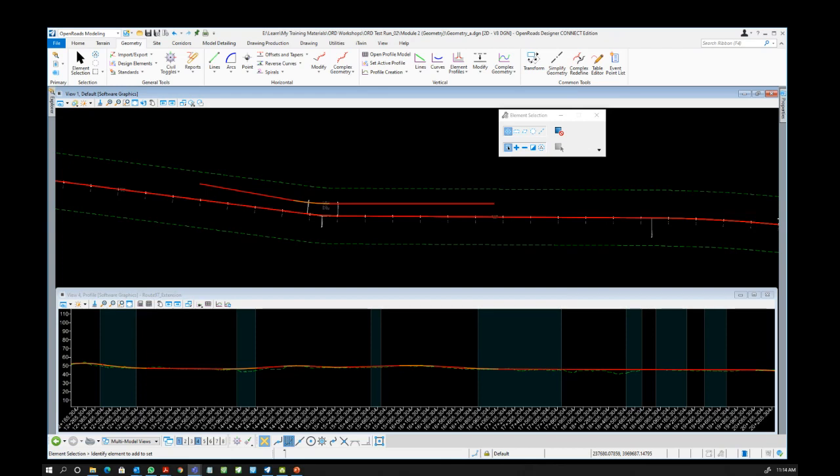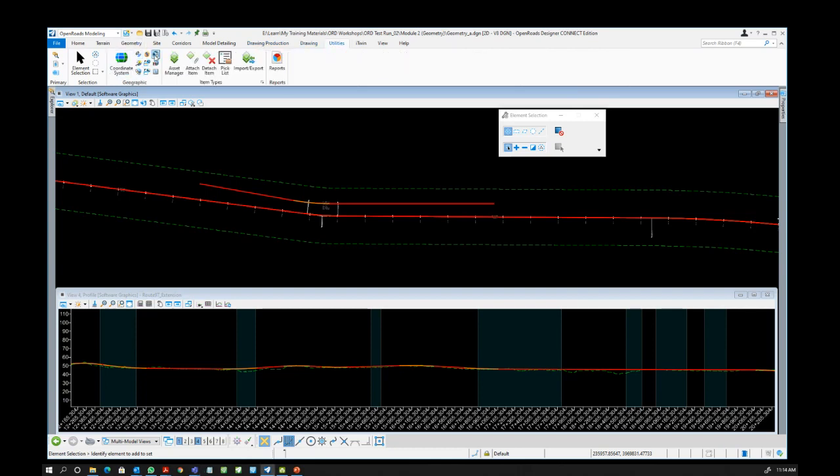How the Google Earth map can be applied to the project we're doing, maybe later. Okay, I think I've mentioned it a little bit for the Google Earth. You just need to go to utilities and then use synchronize your Google Earth. You have to open the Google Earth application to do this, to synchronize your view. So you have to zoom into Google Earth, and then using this tool would allow you to synchronize it to whatever view you have in your application or OpenRoads.